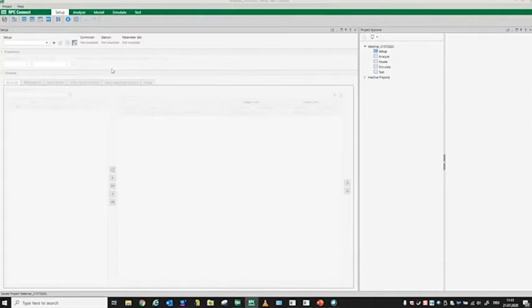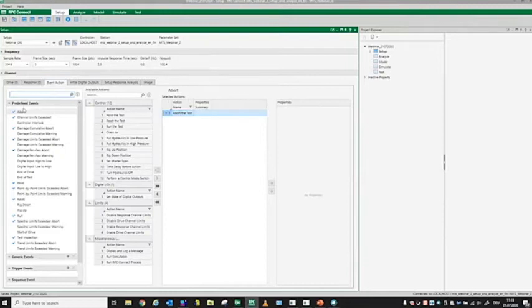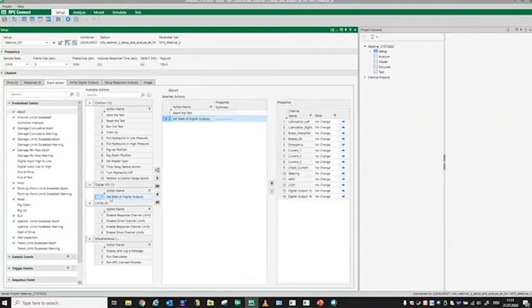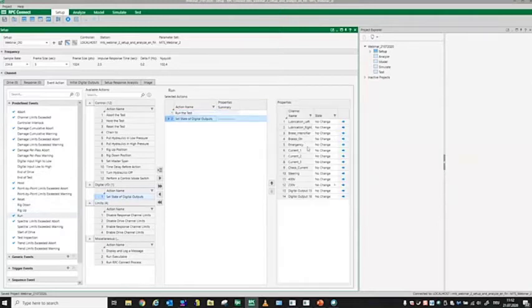We do exactly the same steps and then see the behavior of the new RPC Connect. So we hop into the Event Action tab. And then as you can see, here's the abort section. In the abort section, we had setting digital inputs outputs to low. So now I put that available selection here on the right, and then I can define the changes here as well. So it's similar behavior. I want to have the brakes on low while it's on abort. And if I hop into run, I want to have it on brakes on high, of course.